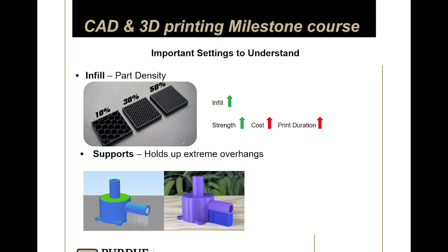But the good thing is, if you're designing a part, you can do your best to design it to not need supports, because supports obviously take extra time, since you need to print the support along with your part. It costs more because you're adding material, and you also add a step of post-processing, right? You're going to have to spend time to remove the supports, and sometimes it can get kind of annoying. Obviously, if your geometry really needs that area of material there, then you can add that support. But typically, because you're designing the part, you have the power to design the need for the support out.